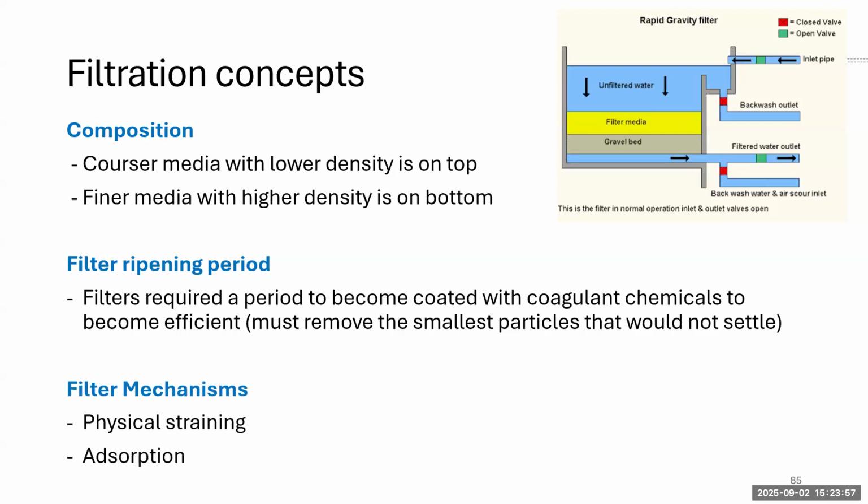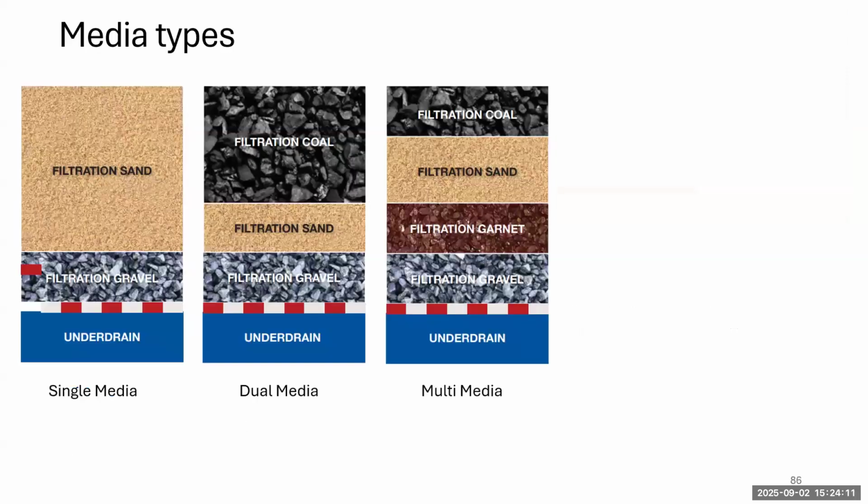Also, there's different filter mechanisms going on. There's not only straining, but there's adsorption going on in the filter. Otherwise, you wouldn't be able to remove very, very small particles that are smaller than the pore spaces between the media grains. In general, there's different ways to stack filters.